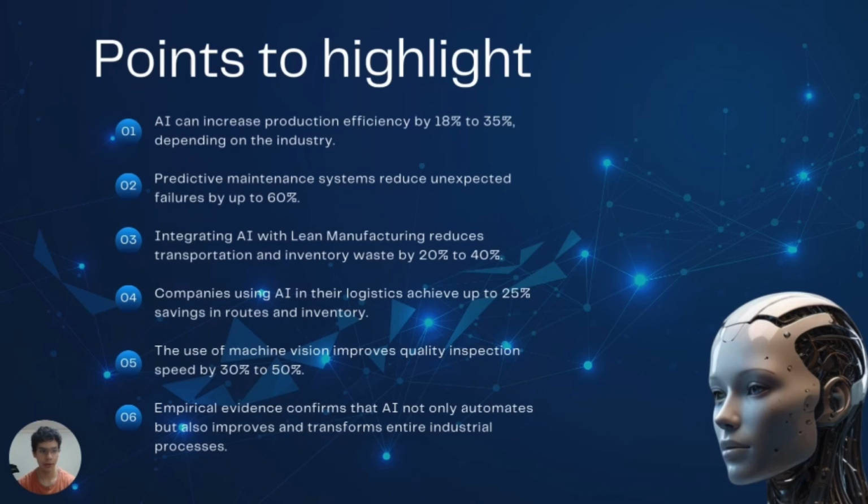And the point number five is machine vision, which accelerates inspection by 30% to 50%. How is this achieved? Cameras inspect 100 percent of parts online with rapid decisions, OK, not OK, and evidence recording. Example: detecting scratches, burrs, missing parts, incorrect assembly, or out-of-tolerance measurements.